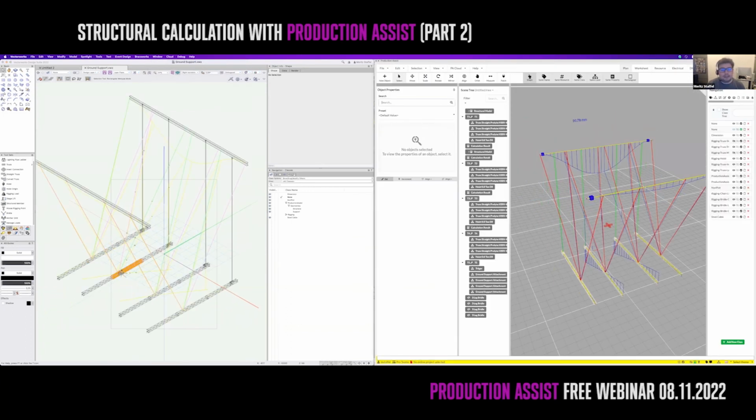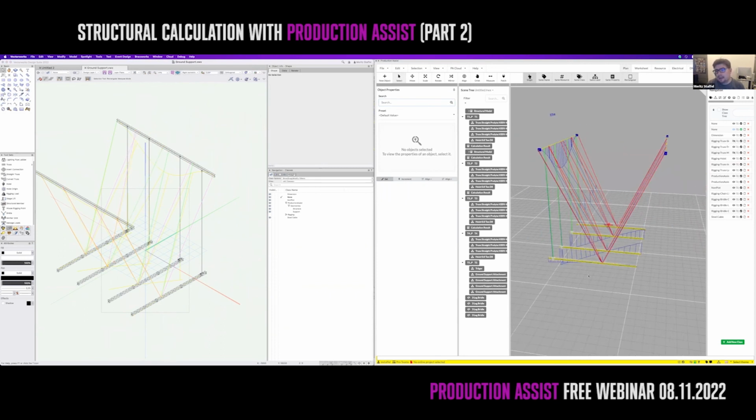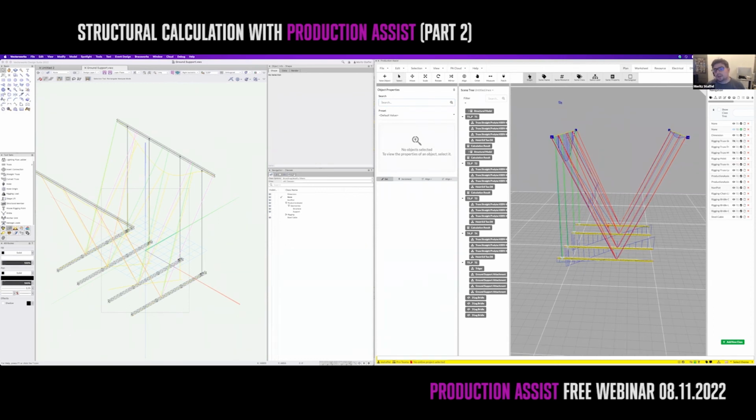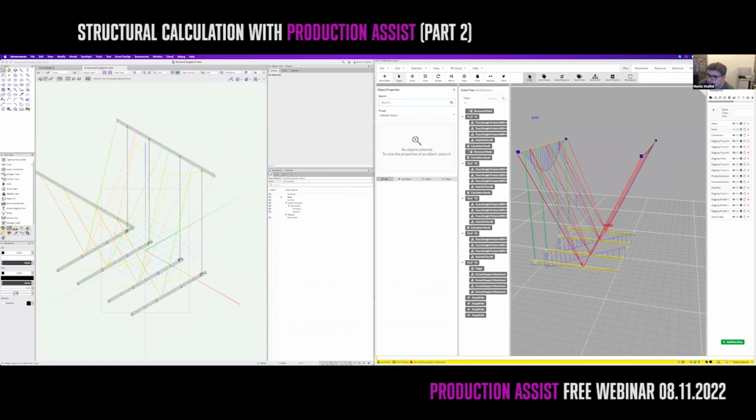What you see in here is that you're actually having structural members to the roof and bridles and hoists mixed. The problem with this is, because the structural member on top is also bending, the trusses also go down. You see the one in the middle going down way more than the one to the right. You also have bridles that are using ropes in order to connect this in here.